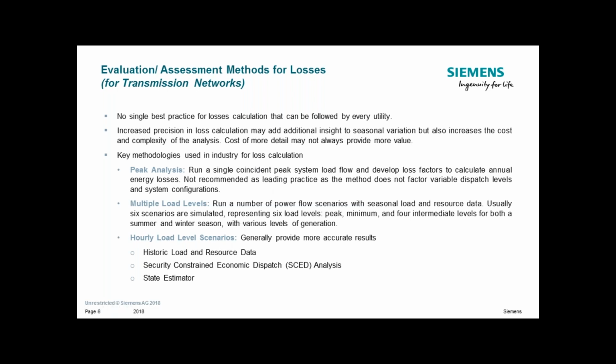For example, nowadays utilities are using digital meters with a UID, a unique ID identification number. You bring these in, directly or indirectly linked with your power system analysis tool, read the data from there, and run your simulation.